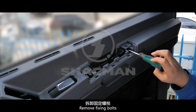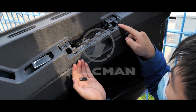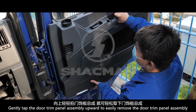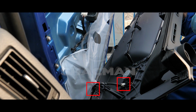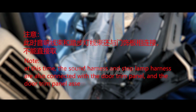Remove the fixing bolts. Gently tap the door trim panel assembly upward to easily remove it. Note: at this time, the sound harness and step lamp harness are also connected with the door trim panel, and the door trim panel assembly cannot be removed directly.